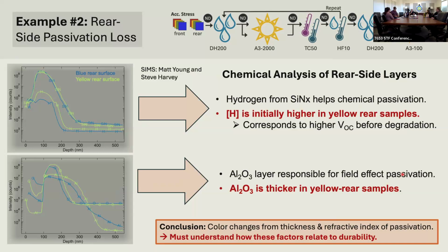I did see one more question pop in here. The question is, have you UV irradiated from the rear side of modules for rear yellow cells in your study? I guess maybe the question is if we see a difference between the blue and the yellow. This is the interesting thing for those yellow rear cells: we illuminated them from the rear and they degraded less than illuminating them from the front. So this is a problem with these cells of having their internal carrier density. It's not necessarily related to the direct UV exposure touching the back surface of the cell.